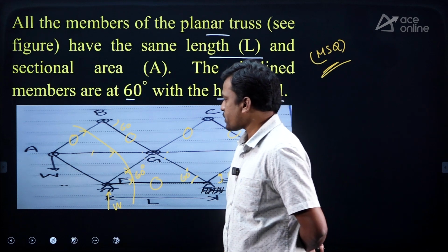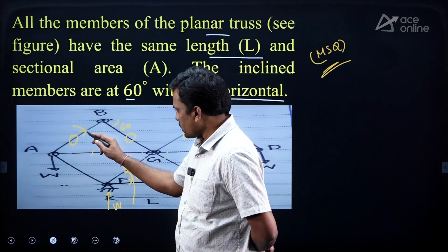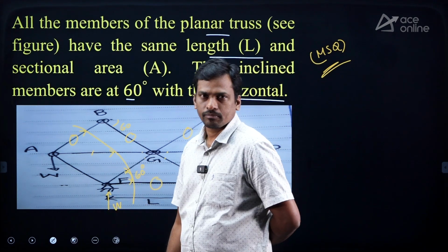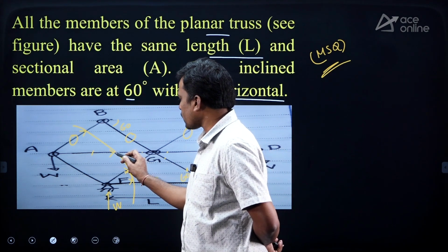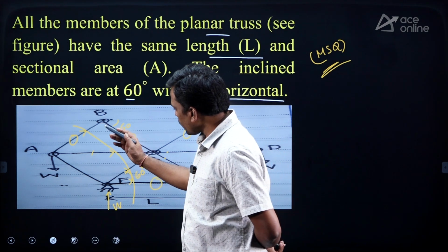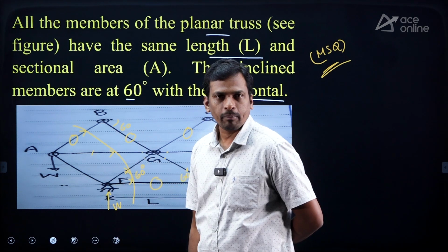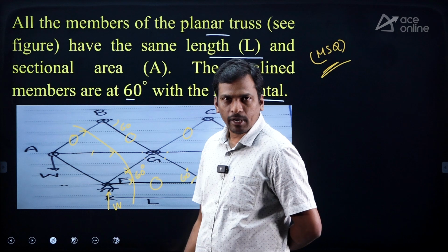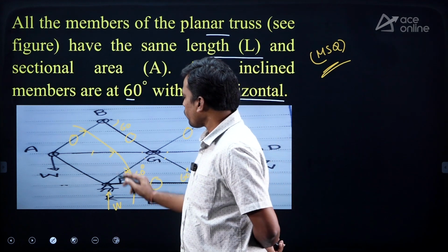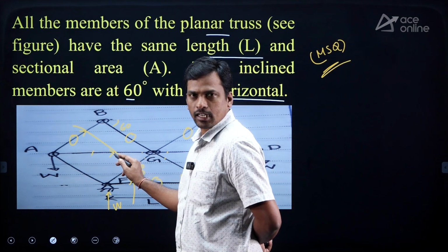Okay. So in method of section, next, check if this section is possible or not. What is the first condition? Section is passing through member AG or not? Yes. And it dividing entire structure into 2 separate parts? Yes. So 5 star is satisfied. Next, preferable equilibrium equations. We have to find the force in member AG, horizontal member, right?